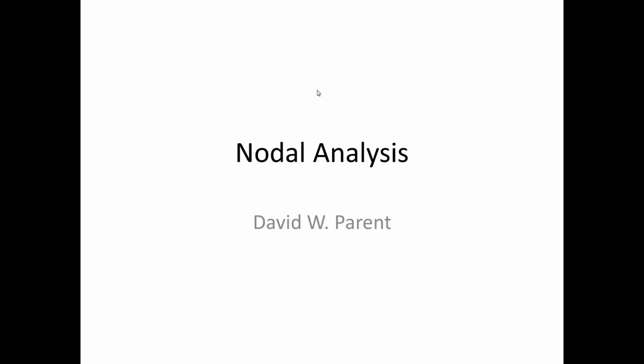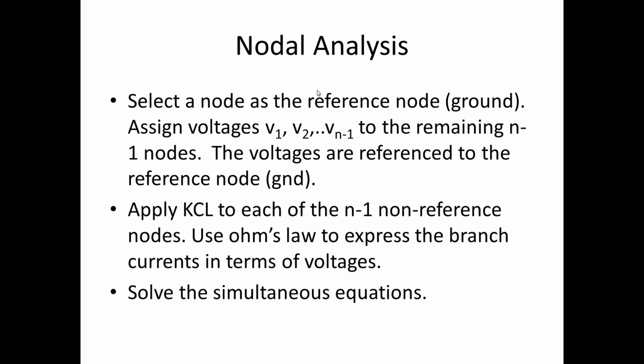Nodal analysis. Nodal analysis is one of two generalized powerful circuit techniques to solve for currents and voltages. In this technique, we select a node as a reference node or ground, then we assign voltage names to the rest of those nodes, and these voltages are referenced to the reference node.